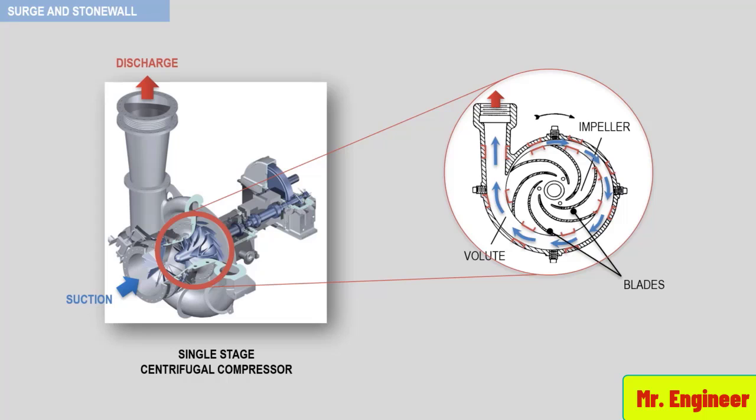As the exit gas angle becomes less, the path the gas must follow becomes longer and eventually can turn back into the impeller, thus causing a backflow. This is one example of a flow discontinuity that limits the amount of energy or head an impeller can produce. Another example of this phenomena could occur in the impeller or blade passage itself and result in backflow.